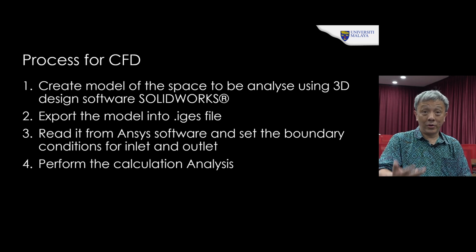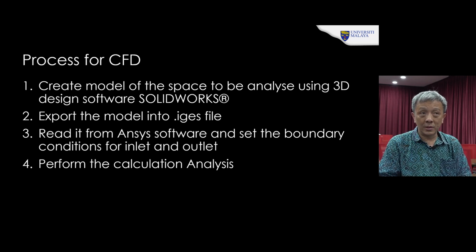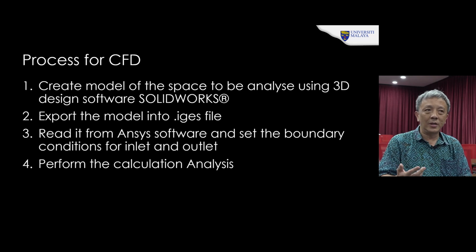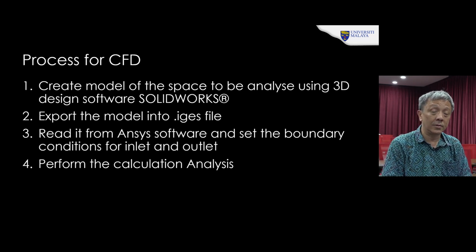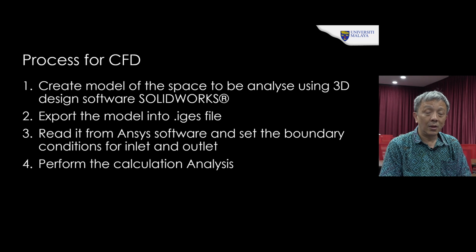The process of creating a CFD is, you need to create a model of the space to analyze using 3D design software, something like SolidWorks, export the model into an IGES file, read it from analysis software, set the boundary conditions for the inlet and outlet, and then perform the calculation analysis. This is what we have done, or not me, but the engineering team has done.